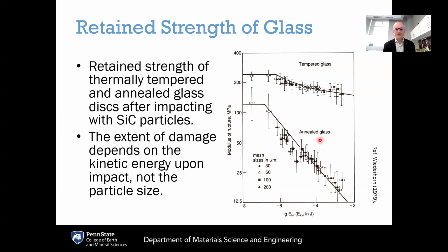when it fractures. This is a feature not only of thermally tempered glass, but also chemically tempered glass and laminated glass. So any time there is stored tensile energy that balances the compressive stress energy that is put into the material. Now, what is the practical benefit of going to a thermally tempered glass? We have an improvement in the retained strength of that glass. The graph here on the right shows the modulus of rupture here.